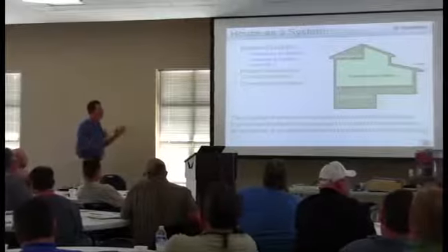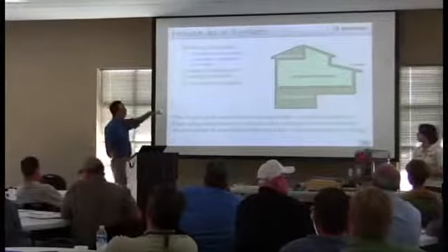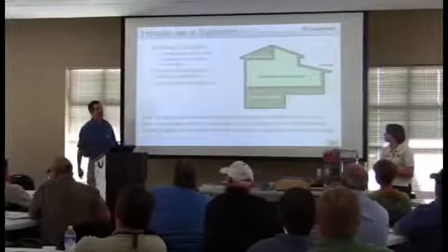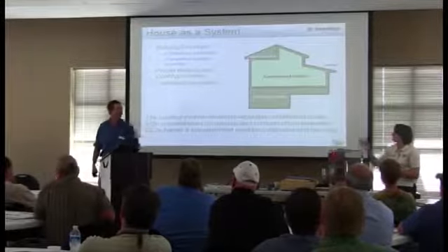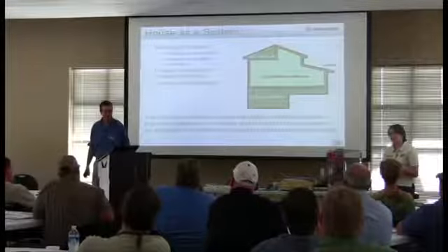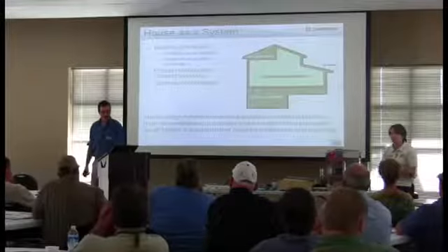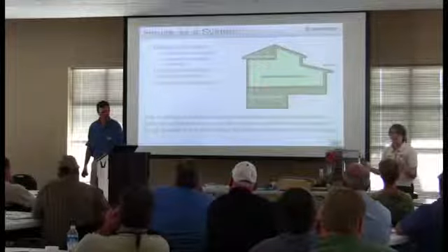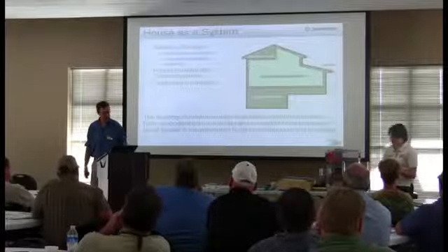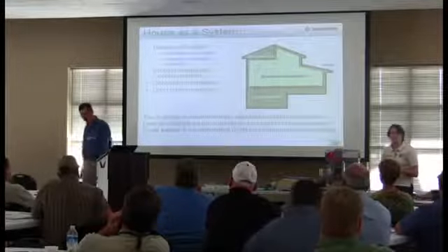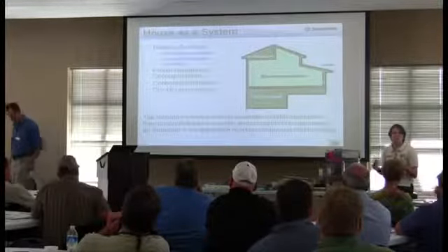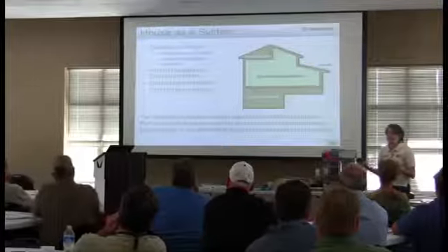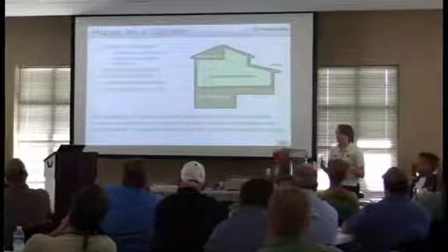But by law, you are not required to do intentional ventilation other than maybe a bath fan and kitchen range hoods. And if you have a great building envelope and an appropriately sized and distributed air system, you're going to prevent moisture from coming into your house. Usually we see moisture coming into the house not as bulk water, but as humidity.